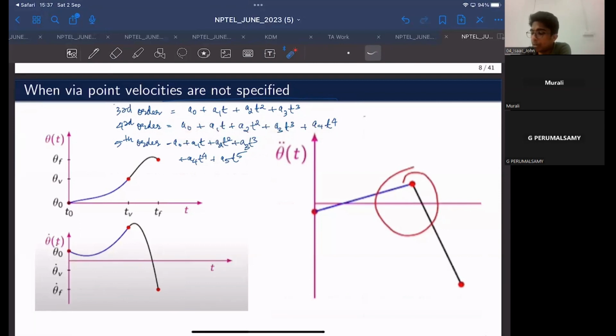So that does not really add up. We can either control initial acceleration or final acceleration. But that does not make it complete, right? In order for it to be complete, we have to be able to control all positions, all velocities, and all accelerations. So the number of equations that we can have from a fourth order polynomial would not suffice.